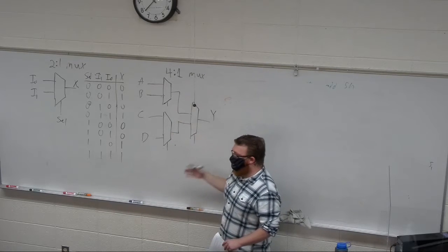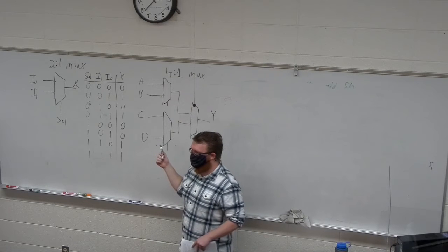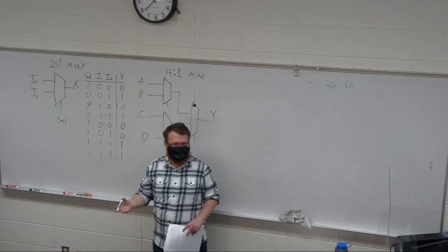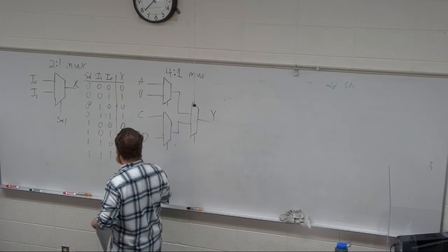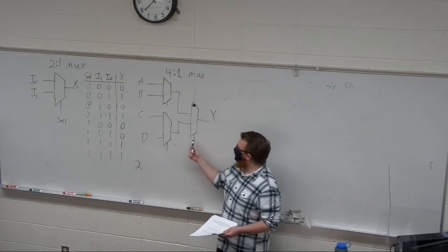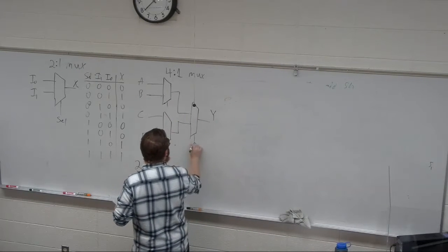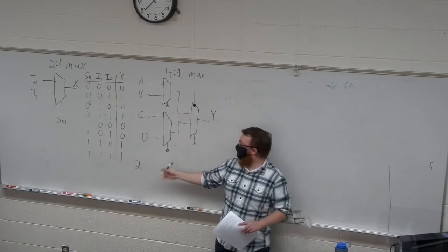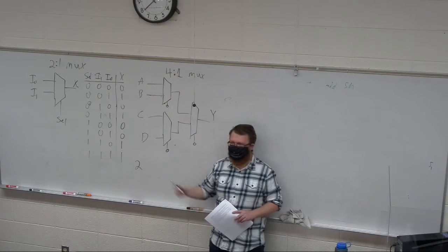All right. So this one, I now need to decide what the select logic is, right? So there's 4 inputs. How many selects should I have if I need 4 inputs? Yeah, so I should only need 2 select channels. Is there a simple way to wire up the selects at this point that allows me to choose A, B, C, or D? Right, because right now I have 3 selects. How do I wire them up such that I can access any of those?